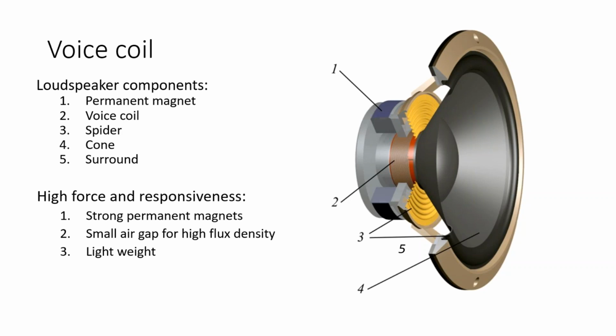The loudspeaker, as a driving mechanism, includes permanent magnets and a voice coil, but then it has some additional components like a spider and this loudspeaker cone, which are used to transmit the mechanical electromagnetic forces developed between the permanent magnets and the voice coil into an acoustic wave generated by the interaction between the cone and the air in the ambient.